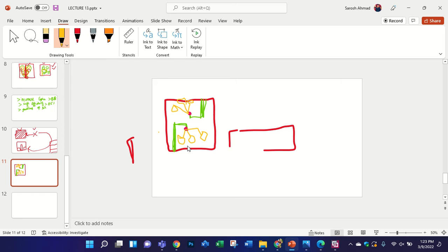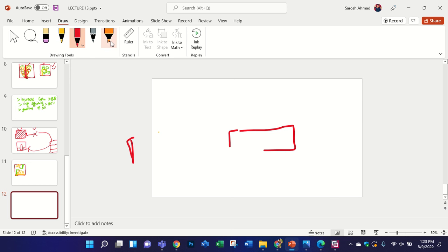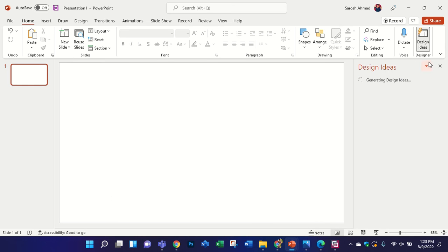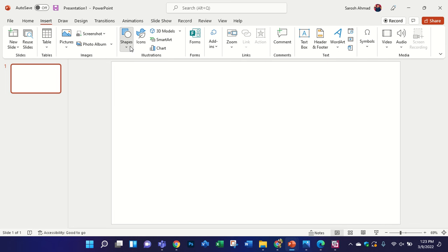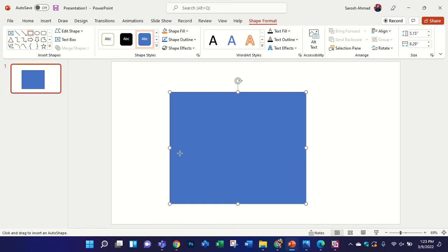We can even use CPW here, a very small size CPW. And also in one paper I noticed one great idea, one most important thing. I saw one paper where they did not use the ground plane in the MIMO antenna, but they even used, let me explain here, suppose this is your substrate, and suppose you are using a cross form antenna.